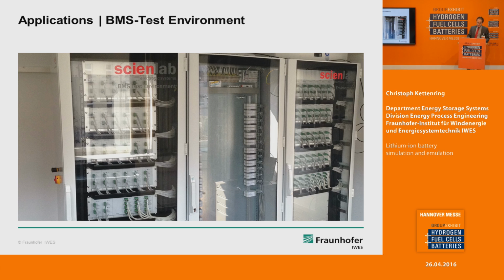And in the middle, you can put the battery management system, and then you can check if the algorithm of the battery management system works correctly, or you see the SOC and the SOH of each cell, and you can compare it with the results of the battery management system of the software.